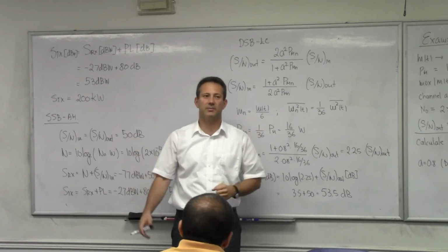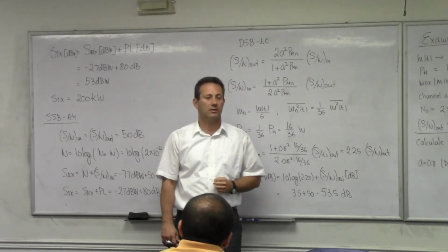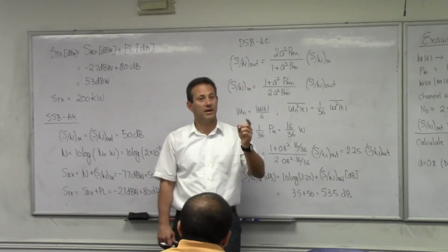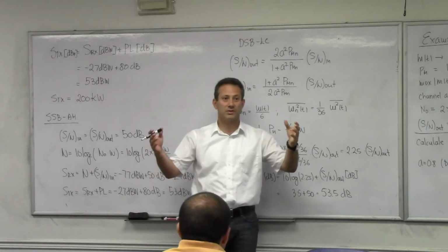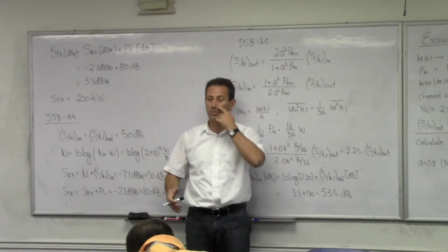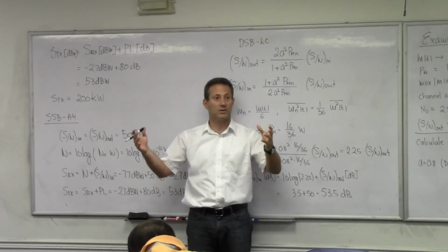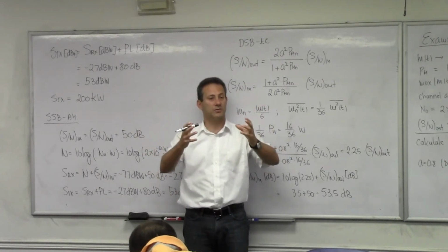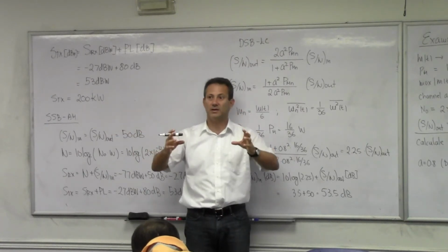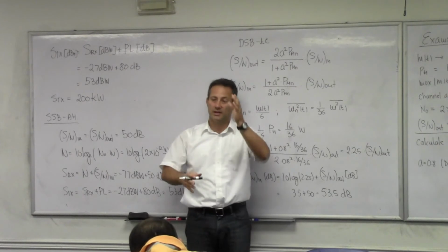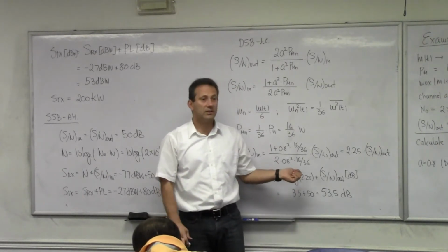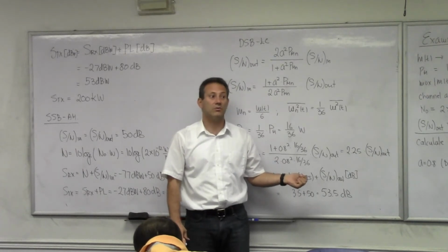Think about what makes double sideband large carrier. The carrier, right? So here's what is happening in double sideband AM. Your signal is composed of two components. One is the actual information, which is m(t) cosine 2 pi fc t, but there is embedded in there a pure sinusoid that sits in the middle. That's your carrier, the large carrier piece. In the receiver processing, the large carrier is thrown away.